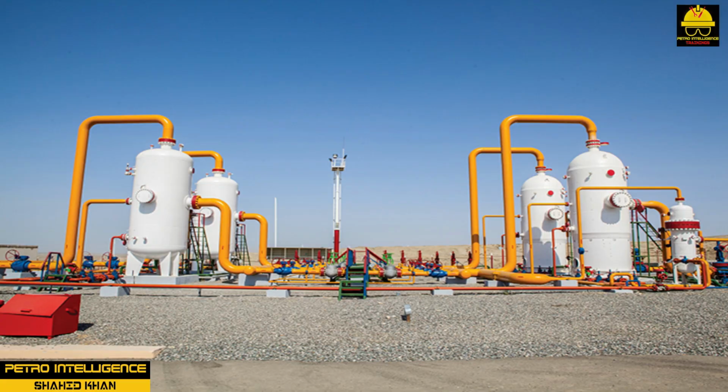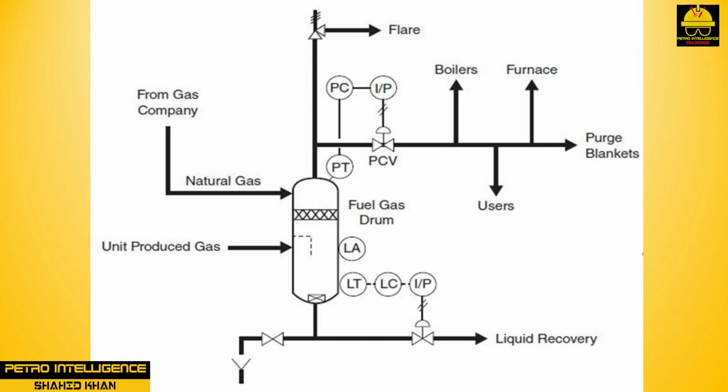Gas systems. Most industrial manufacturers purchase natural gas (NG) from suppliers. A high-pressure pipeline generally delivers gas to the plant. A pressure letdown station located near one of the plant entrances meters flows to the plant. The letdown station consists of multiple control valves, 2 of which are normally in service for backup. Additional valves are provided for peak loads such as unit startups.